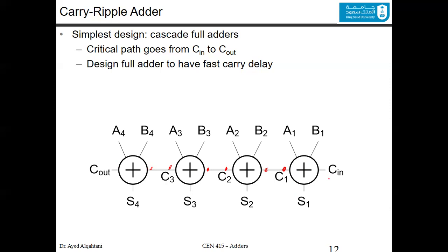And so you can see here why we care about the carry. In the carry ripple adder, the carry is actually the bottleneck. You have to wait until this is finished, until you get the last carry out. So the last carry out actually depends on the first one. But this sum is based on only those 3, and so on. And the last sum is based on the carry number 3, B4, and A4. So this is the bottleneck, and this is why we care about the carry, and we also define the generation, propagation, and kill signals for them.